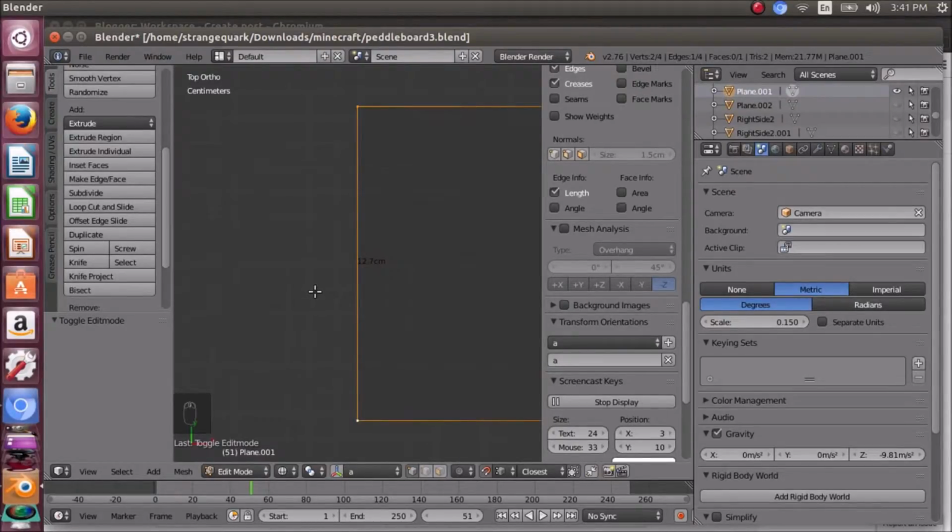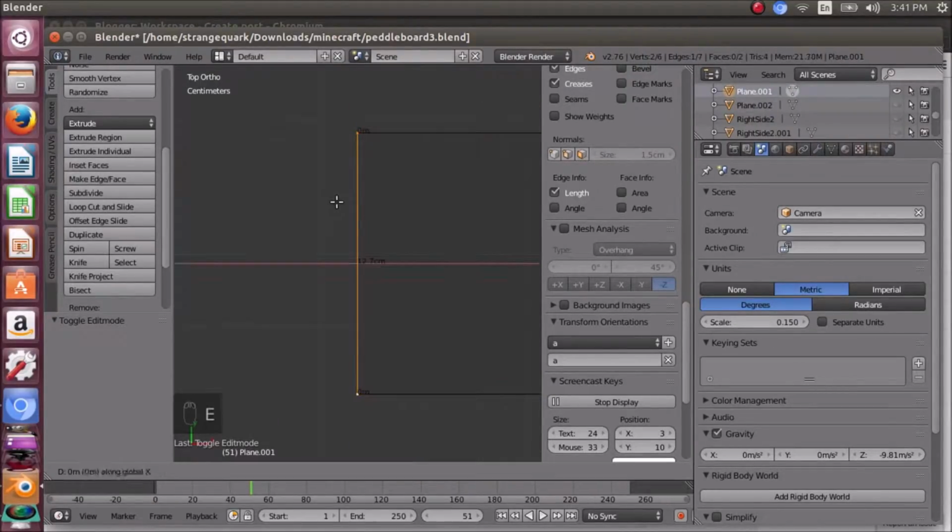So we can kill two birds with one stone by selecting two vertices and then extruding these vertices on an X restricted axis basis. To do that, we just hit EX, and I have the numbers memorized for extruding it to the appropriate thickness for the desired wall, which is 5.08.